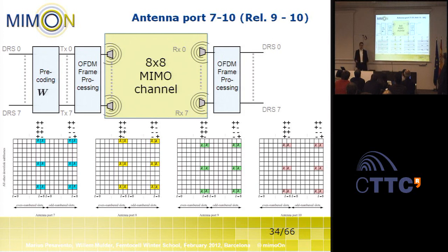So that's quite a requirement: for 1 millisecond, the channel should be approximately constant. But the idea behind this is that if you use higher order MIMO, then you would only do this if you have favorable channel conditions. So if you are moving in a high-speed train, nobody expects that you can achieve, let's say, 1 gigabit per second download.